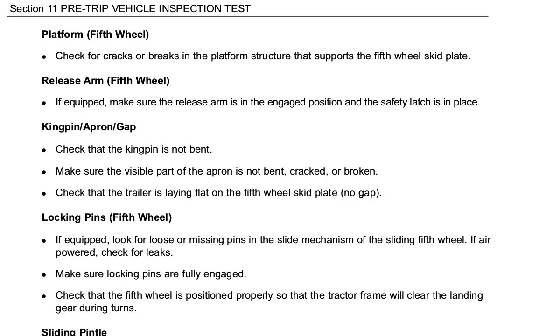Platform, fifth wheel. Check for cracks or breaks in the platform structure that supports the fifth wheel skid plate. Release arm, fifth wheel. If equipped, make sure the release arm is in the engaged position and the safety latch is in place.